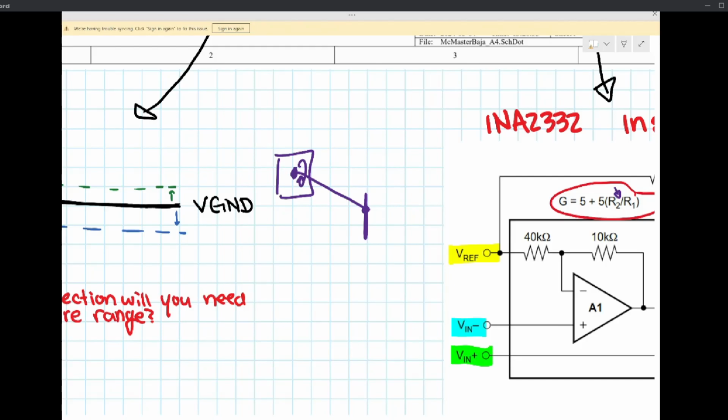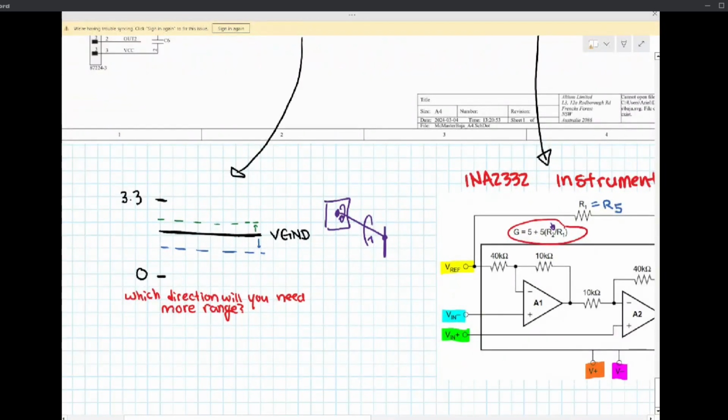And all of a sudden you hit the brakes, and your engine is going to be back driven by your wheels. Your wheels are going to want to stay still, and you're going to see a reverse torque in the opposite direction on your axle. It was a debate last year, and it kind of still is, which way, on the acceleration side or on the deceleration side, are you going to see more torque through that axle?